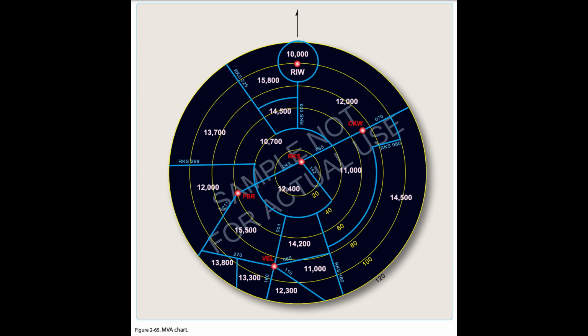Air traffic controllers use MVAs only when they are assured an adequate radar return is being received from the aircraft. Charts depicting MVAs are available to controllers and have recently become available to pilots. They can be found at the FAA website. Situational awareness is always important, especially when being radar vectored during a climb into an area with progressively higher MVA sectors, similar to the concept of MCA.